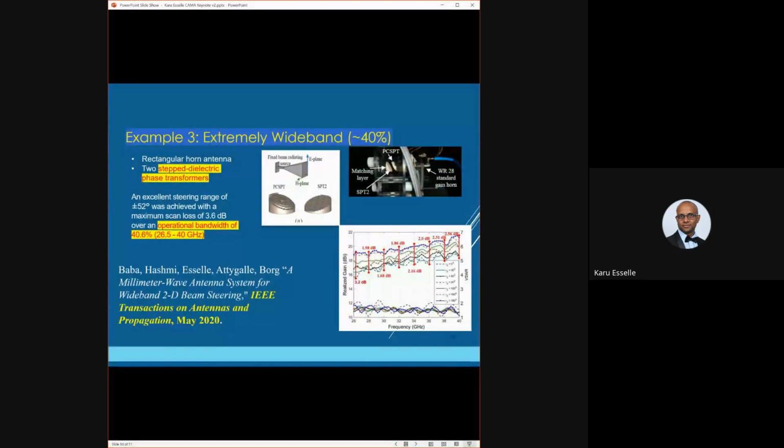Still you can, when you design the cells, you can use some far field approximations. The cells are designed as unit cells using the eigenmode solver, for example, unit cell excitation in CST and HFSS. Yes, sir. Apply one mode from one end and try to get the phase shift from one port to the other. But at the same time, you have to make sure that the reflection is less.